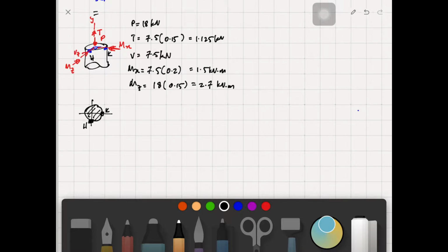And if you can remember, the transverse shear, the system is not that straightforward. We need to know all the terms involved, for example, the first moment of area denoted by a capital Q. So I'm just going to break it down into computable terms, so it is easier for us to use when I list down the equation for each of the stresses.